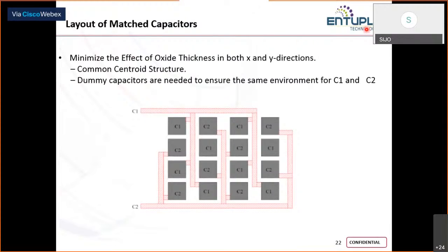Also, you can go for a better aspect ratio in your layout. If you instantiate a 10 picofarad capacitor directly, it will be of huge size and it will be tough to get the aspect ratio. Always, when you do a layout, we look for a better aspect ratio. When I say better aspect ratio, I mean the L into W values, so the area. So we always look for a rectangle kind of shape from the top view, or a square shape basically.